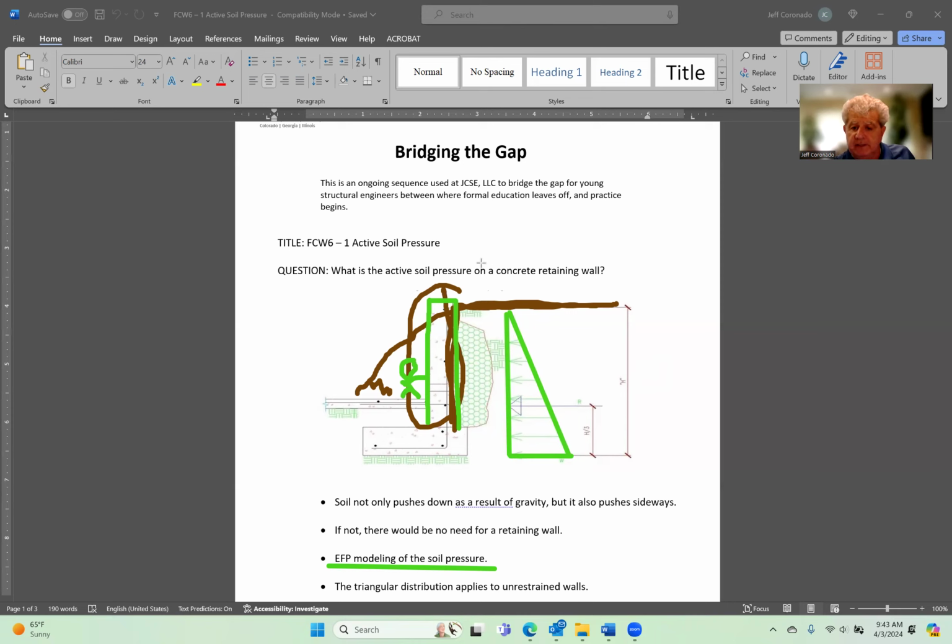One of the important distinctions, which is why I stressed it at the beginning, is that this is a cantilever retaining wall. Let's say hypothetically this were a basement situation where there is a slab, or a floor, up here that also restrains the top of the wall.